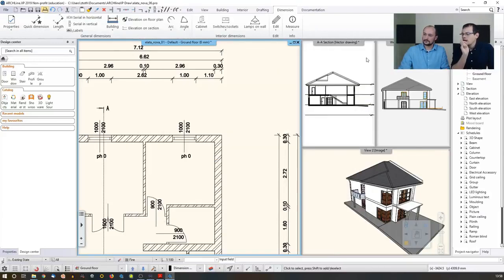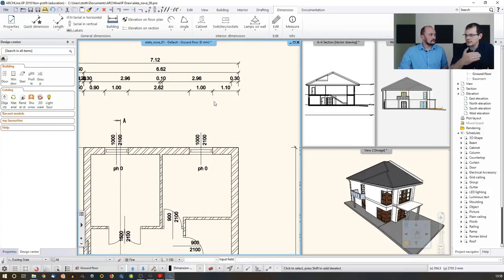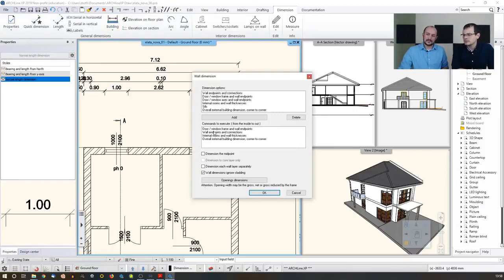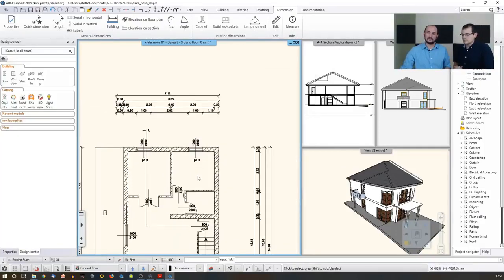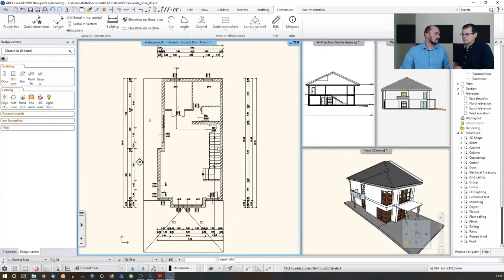Yeah, perfect. A question from my part: what does the order of these dimensional lines depend on? So why do I see that line with the window measurements first and the others next? These depend on this list, how I assemble this list. So I selected one item, I added it here, and then the second one, the third one, and the fourth one. So this makes up the order then which appears around the building when I make the dimensions around.